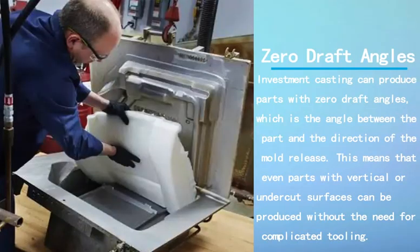Zero draft angles. Investment casting can produce parts with zero draft angles, which is the angle between the part and the direction the mold releases. This means that even parts with vertical or undercut surfaces can be produced without the need for complicated tooling.